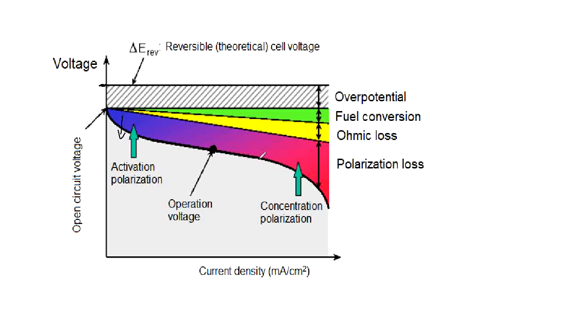Then as we increase the current drawn out of the fuel cell, we get to the point where the polarization loss further increases as the so-called concentration polarization loss, which is caused by the limited mass transfer on the electrodes. So this was the tutorial on the fuel cell, how it works and how to calculate its parameters.